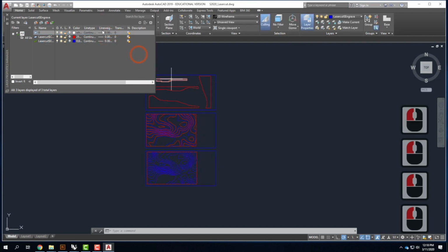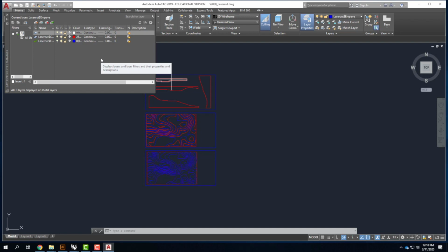An important note about the laser cut: when you go to do the laser cut, make sure that you're printing at full scale. Don't scale the drawing. Don't scale the fit. It's okay if the border on the outside is going to get cut off. That's okay. Don't scale the fit because otherwise your steps aren't going to be the right sizes. So we want to make sure that they are in fact the right size when you go to do the print. If you have one of the lab techs help you do it, make sure they don't scale the fit because it does make a difference.